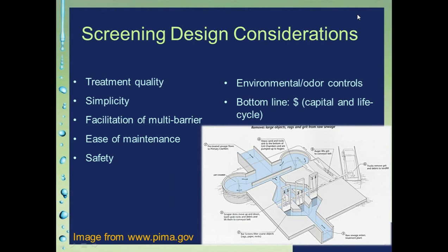So we want the treatment quality, but we also want it to be a simple system, easy to operate either automatically or by operators. And we want to facilitate the multi-barrier approach, so that if there is system failure, it's very easy to have some level of redundancy or some level of treatment should failure in a single stage occur. And then ease of maintenance, safety, environmental controls, etc.